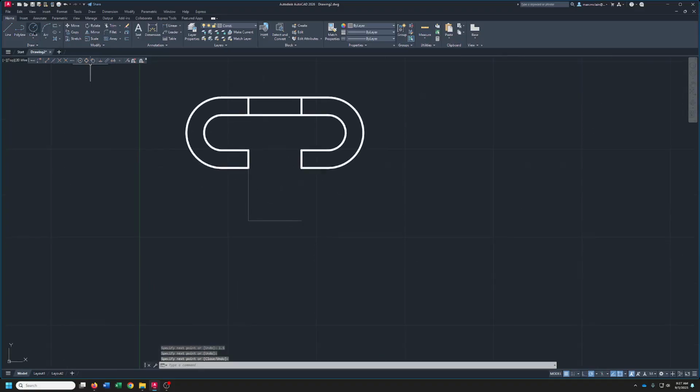Now, I'm going to do a 2-point circle. Okay? First thing you want to do, get back on object lines. 2-point circle. Right in the middle of that. Now, if the radius is 0.75, that means the diameter is 1.5, and we want diameter here. So we're going to type 1.5, and that gives us the main circle.